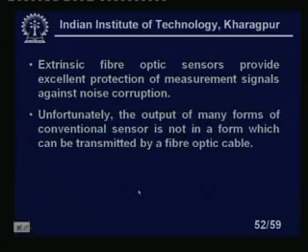So, that is inherent to any optical fiber sensors: it is immune to electrical noise, surge, anything. It does not matter. And moreover, two optical fibers can go side by side without having any crosstalk, which is not possible with electrical wires. If I take two thermocouple lead wires going parallelly, and there is a surge in one, that will affect the other thermocouple lead wires also. So obviously that will affect the output which you will receive.